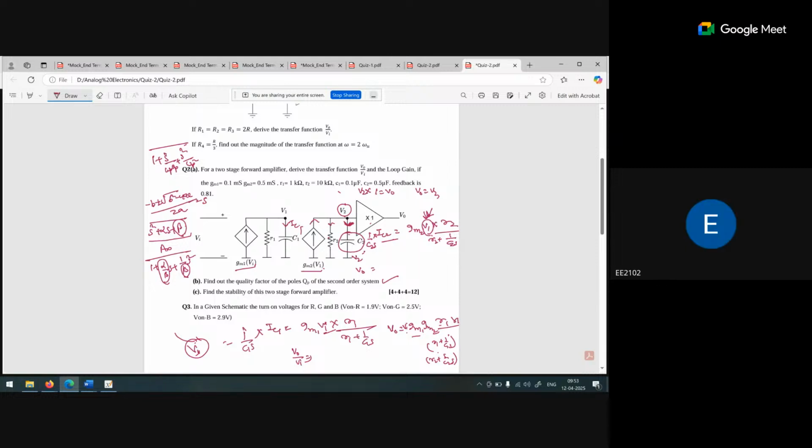Okay, got it. So that's why it is better that you calculate the pole values and identify that two poles will be lying on the left half of the S plane and both poles will be different. If this is my S plane and I am getting two poles here. If two poles lie at the same position, we can say the system is marginally stable. We can't say this is a completely stable system.